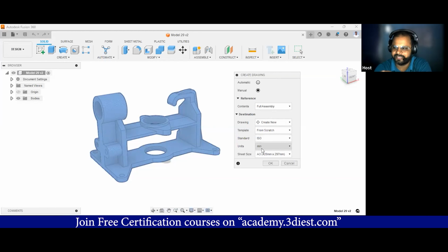In most cases when you are preparing an engineering drawing for the workshop, mostly for small parts, the A3 paper size is enough. Otherwise, if you are preparing architectural, civil, or structural drawings, you will need a bigger paper size like A2, A1, or A0. But in the case of manufacturing drawings for precise parts, A3 paper size is enough all the time.